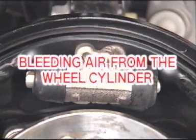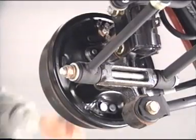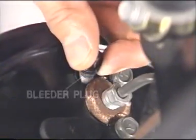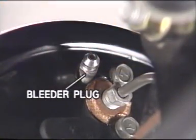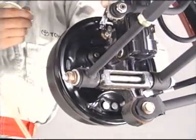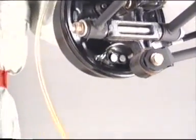Release the parking brake. Remove the bleeder plug cap from the bleeder plug. Connect a vinyl tube to the bleeder plug and insert the other end in a container half full of brake fluid.